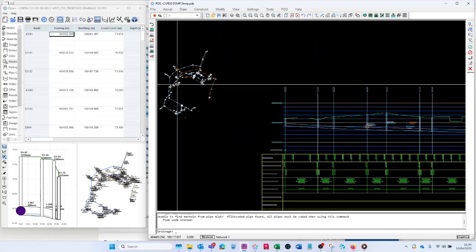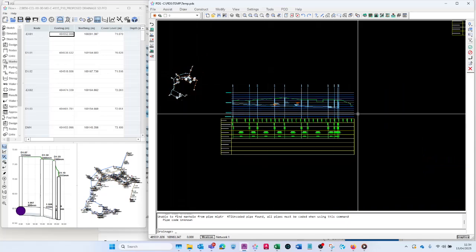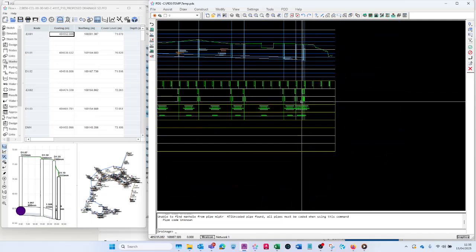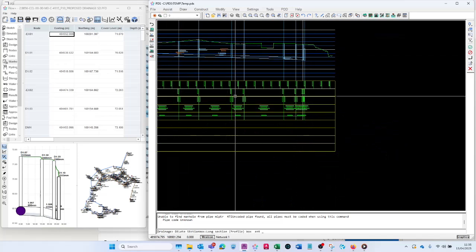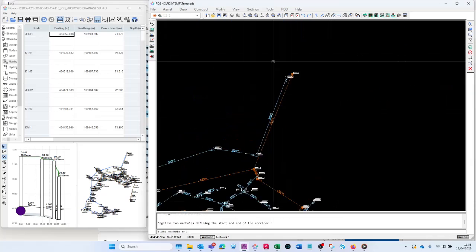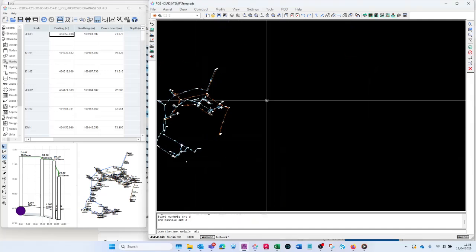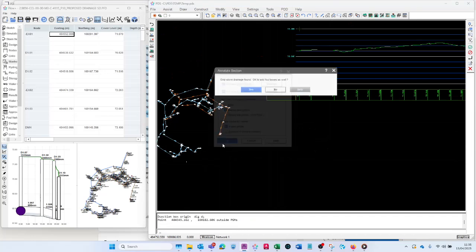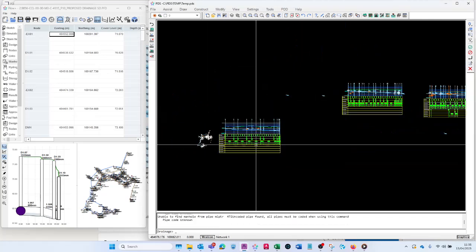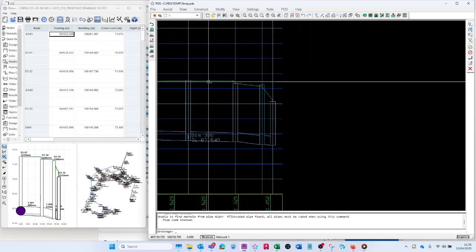What PDS has done is taken a slice of the site through there like a cake and has drawn that, and it stays fixed. So if I want to update the ground levels here, then I have to regenerate this section. So I'm going to delete the section and I'm going to redo the corridor from there to there, go okay, go yep, generate the crossings, okay. There, 8 and 3 is the correct lengths, and there the ground level has been amended.